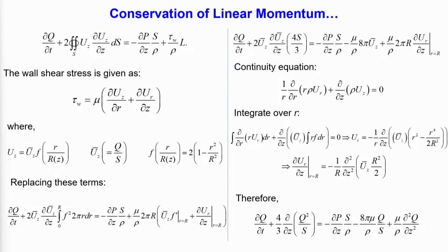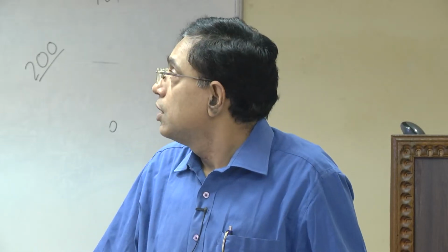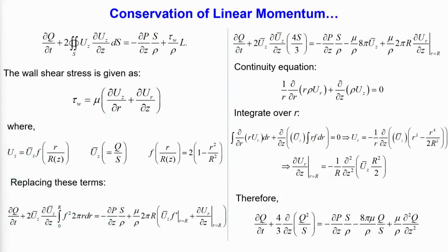What is there is you have integrated your governing equation over the control volume, and that is alright, I mean there is nothing wrong with it. So, in that integral expression, the only approximate thing which is giving you an approximate answer is the velocity profile. So, if you have by some way a means to give it quite well, your answer also will be quite well. So, with this particular example you can now have this velocity profile, and so with this velocity profile you can do the integration analytically and you will get that equation which is there at the top,